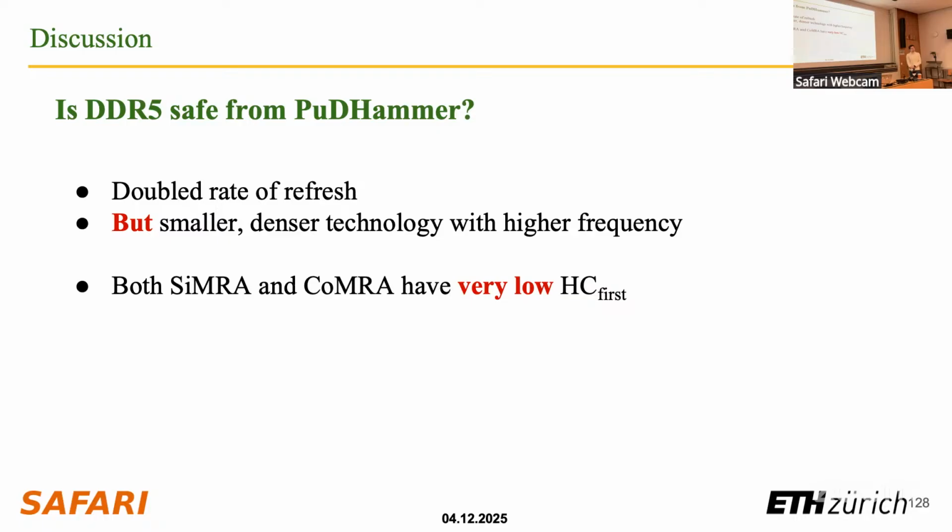operations. This is a valid concern: you're doing something wrong according to the datasheet, right? So you're violating it. You're doing what is out of spec. We actually had a lot of experiments that we didn't put here because it would be 30 pages of paper, to make sure that this is really processing using DRAM. One thing is that the bit flip directionality in the paper is very different from RowHammer, but it is very close to RowPress, which you wouldn't expect.